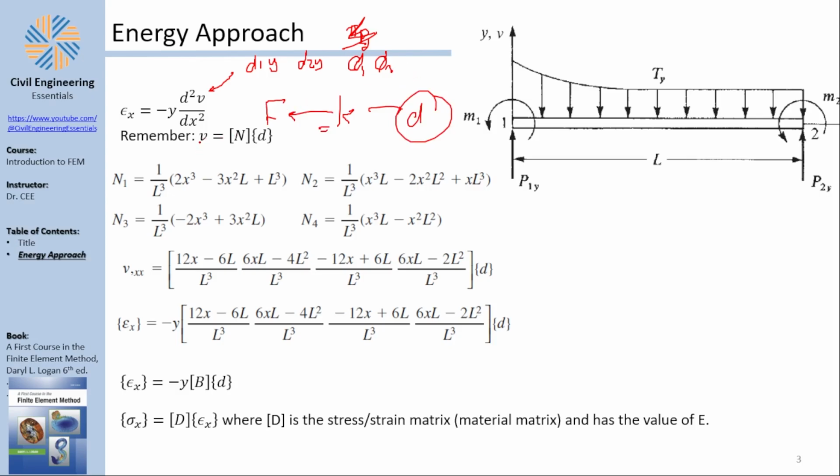And we can do that by saying the deflection field is going to be the shape functions multiplied by the displacement. Now, the shape functions are something I explained before. In the case of the beam, I have 4 shape functions. Also, if you don't remember that, I explained the shape function under something called the interpolation functions or the mixing functions. So I hope you can remember that. Now, those shape functions are already given. We have talked about them in previous videos and how we derive them.